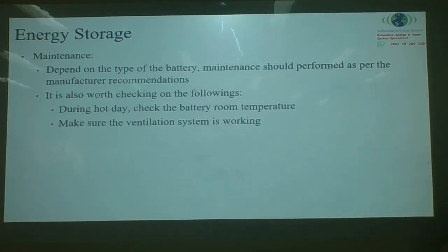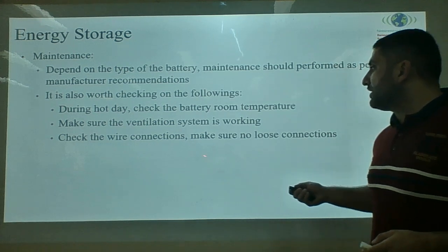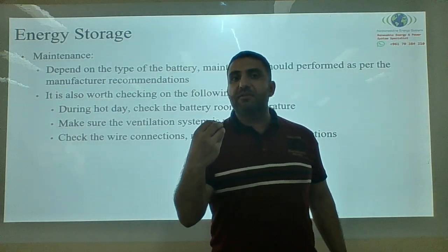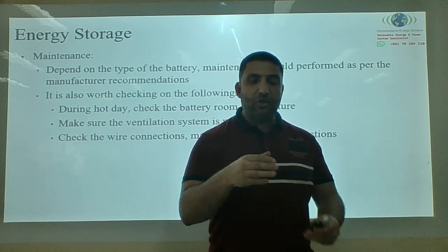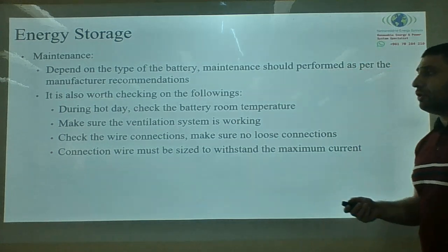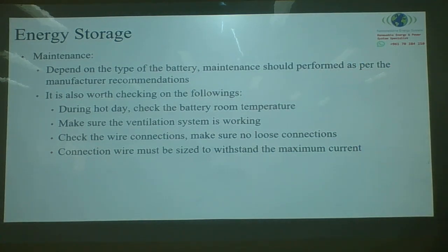Make sure the ventilation system is working well. Check the wire connection, make sure there's no loose end, and also check the sizing. Loose wires could cause corrosion, depending on the connection. Connect the right terminals together. Connection wires must be sized to withstand the maximum current.